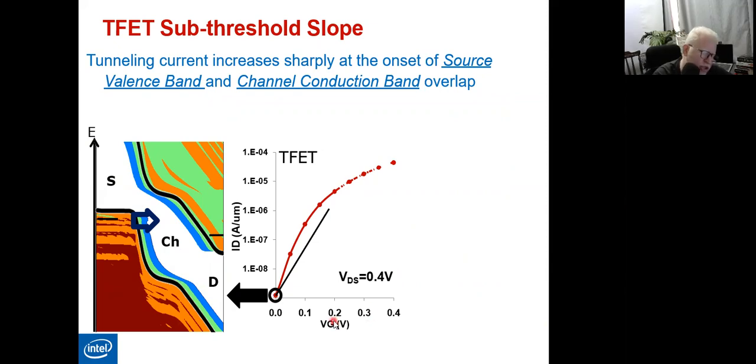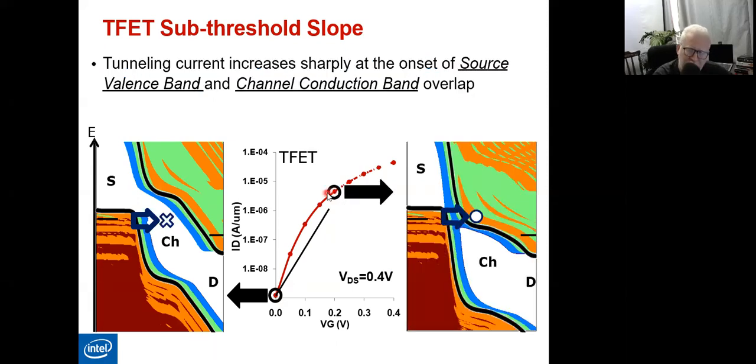Whenever the gate voltage is equal to 0, then your drain current is equal to 0. You don't have a current flow. So if the gate is 0, the drain current is equal to 0. What happens if we increase the gate voltage, to be above the threshold voltage? Simply, what will happen is that this channel will be narrowed down somehow, and accordingly you can see that. Let's now start to plot a line just to demonstrate the idea.